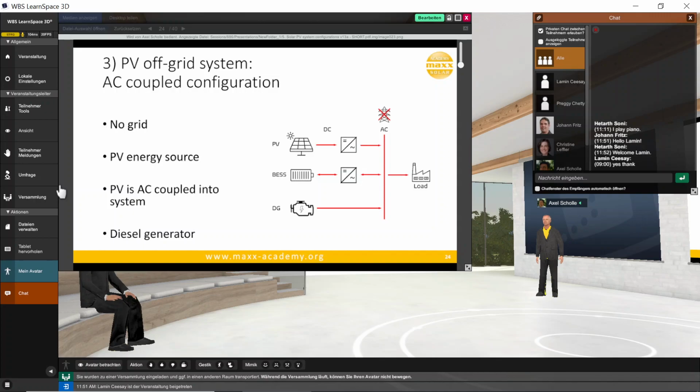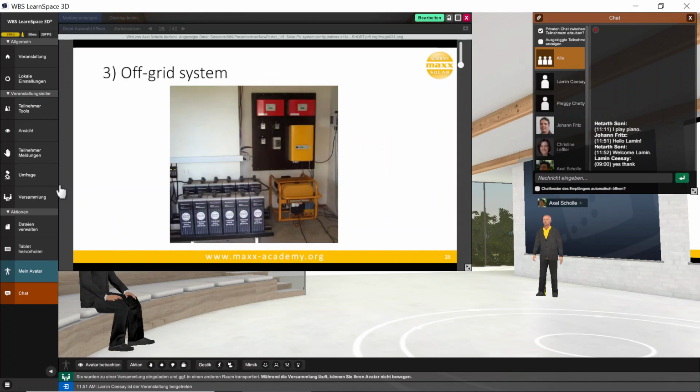So I think here you can see an actual system, fairly small system, but I would say it's residential. You've got your acid batteries on the left. They look like flooded batteries. You can see those two lines at the top of the battery cells where they will show the electrolyte. Then you've got your battery inverter. Sorry, I've got my laser here. So this is the battery inverter, obviously.